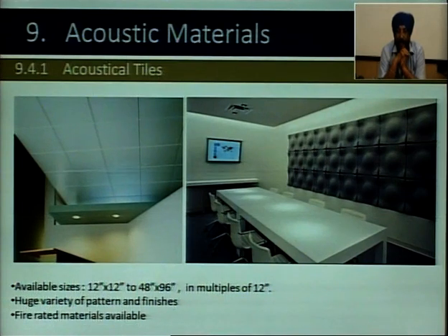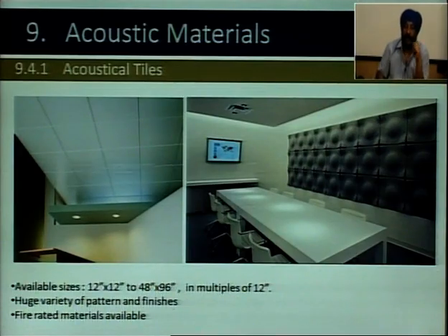So, it is all the ingenuity of the architect how to use these acoustic materials, available in sizes of 12 by 12 inches and even 4 feet by 8 feet, in a huge variety of patterns and finishes, and they are fire rated also. The acoustic materials come in fire ratings of 1 hour, 2 hour, 4 hours even. So, the price of course is dependent upon its fire rating.